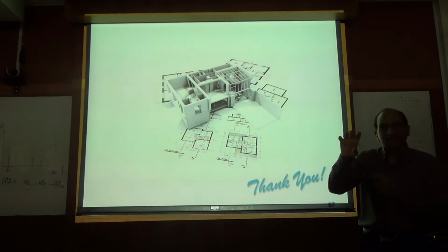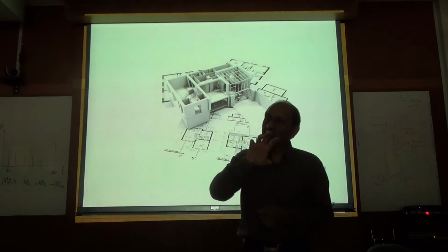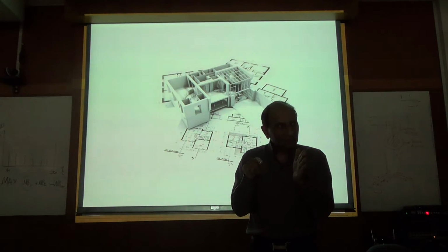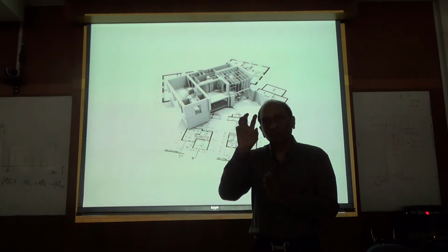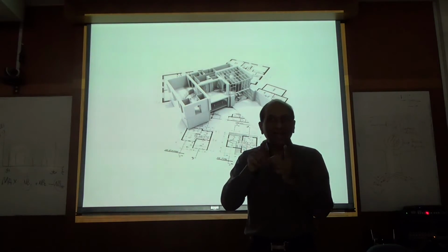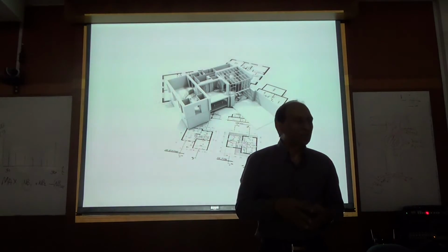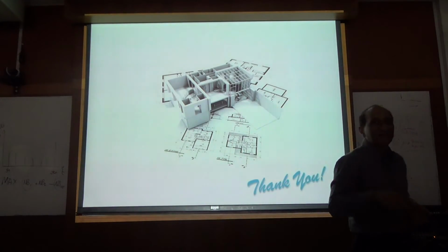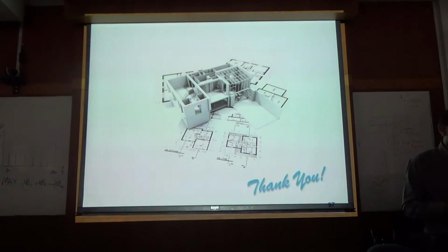Typically, hinge length is equal to the depth of the beam or column. So if you multiply the curvature by the length, then it will become rotation. So you can plot moment rotation, and hinge length is typically equal to the depth of the beam. So you can also calculate moment rotation curves. It's the same as moment curvature, just multiply the curvature by the length h, right? It's the same thing, just a different way of looking at it.